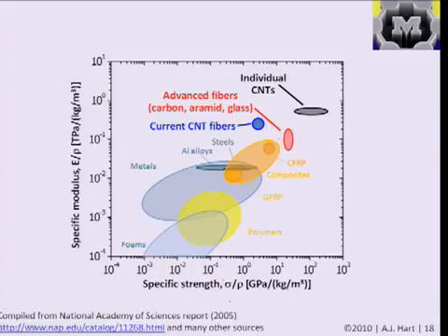So we previously saw this chart that's designed to look at materials with high stiffness and high strength per unit weight, but it can also apply to this discussion because everything's divided by its own density. So we can see the universe of materials here. And there's the arrow. Things like foams and polymers have relatively low strength and low modulus, or low stiffness, and metals get a bit better. And composites combine attractive attributes of different materials and push this out farther.